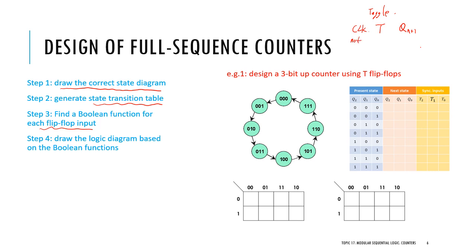Say we are using a rising edge flip-flop. If it's not a rising edge, then it doesn't matter what the T value is, the output will not change. It always equals Qn, the current state.